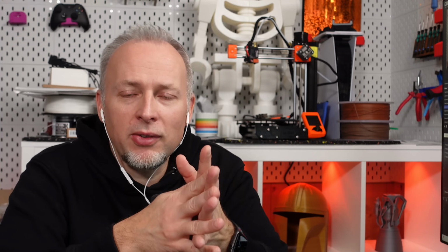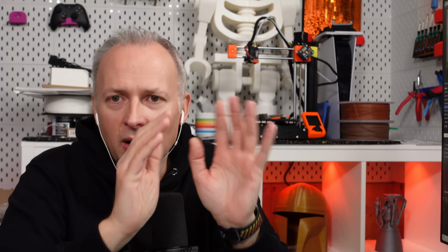Before we spend more time talking about examples, I want to talk a little bit about the principles of what's happening behind the scenes with this program. What I'm using in the background is a programming language called OpenSCAD. Probably a couple of you already know what OpenSCAD is. A lot of the parametric models on Thingiverse are based on OpenSCAD, and you can basically change parameters and get different results. Like you have a sign and you want to change the text, and the parameter for that is the text, and also the dimensions of the sign could be parameters.